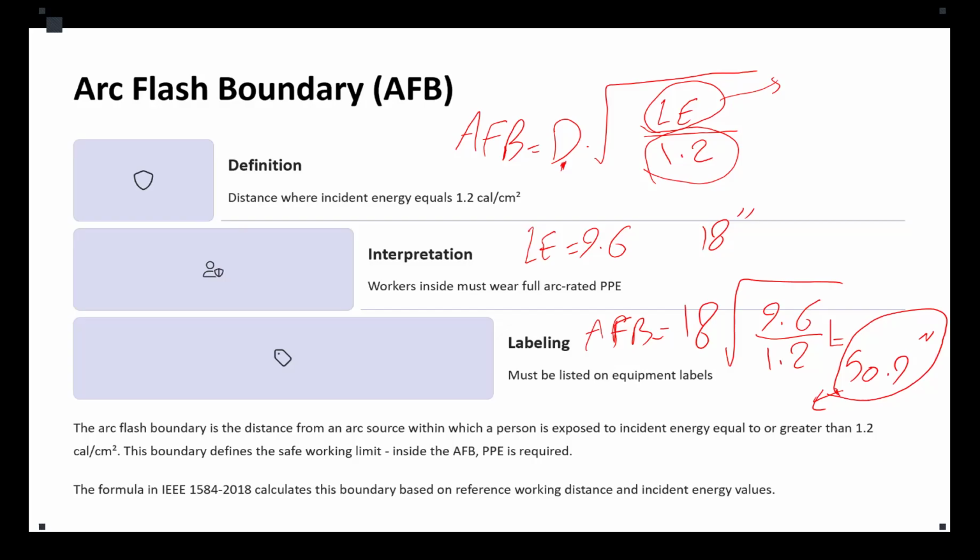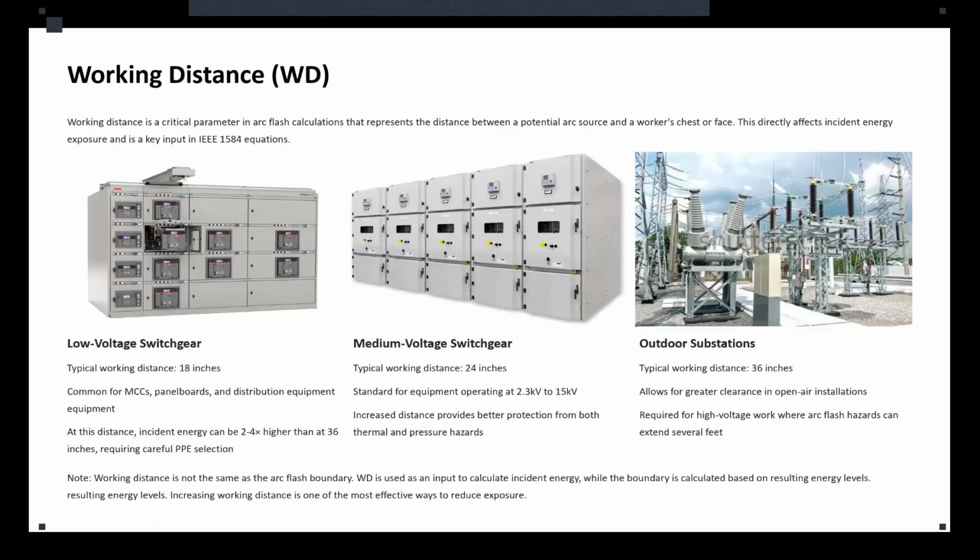Okay, so two different things. Arc flash boundary is only for the thermal radiated safety. Arc class is something else. You need to consider that individually. Now, at this point, we explored two foundational ideas in arc flash. One was the incident energy, which is the thermal exposure from an arc, and the arc flash boundary, which is the distance where the exposure falls below the injury threshold.